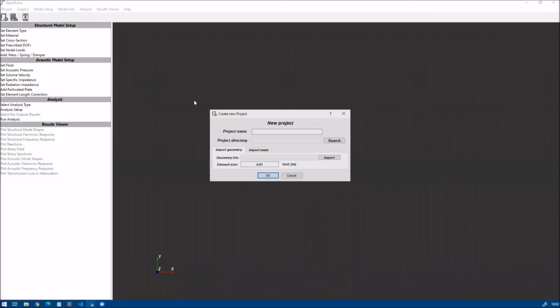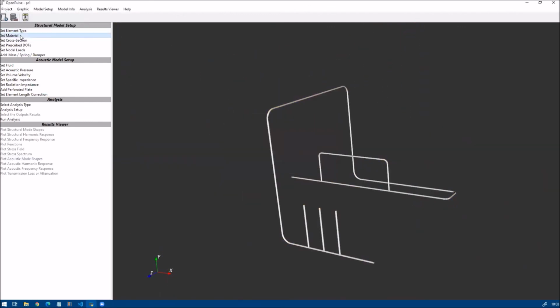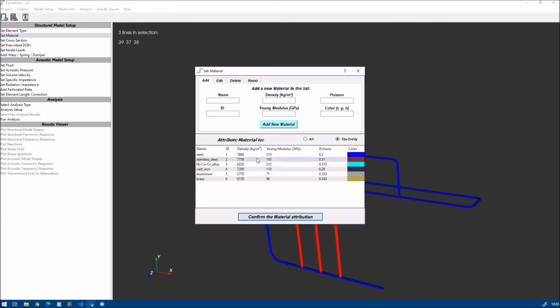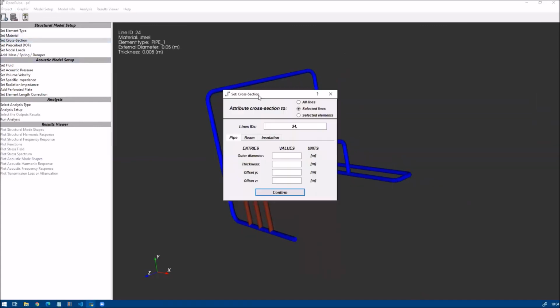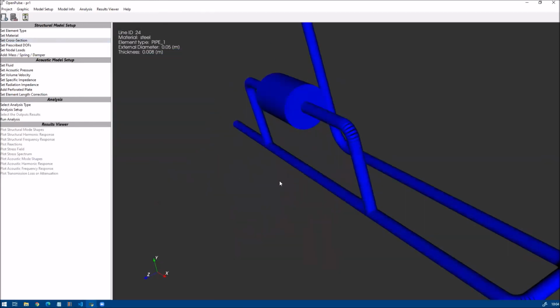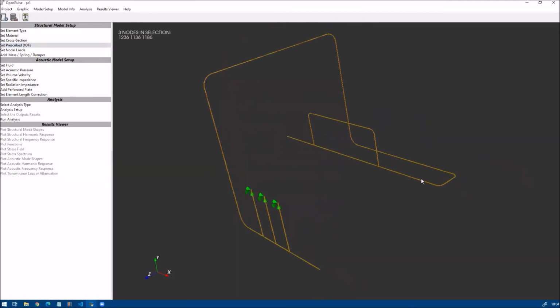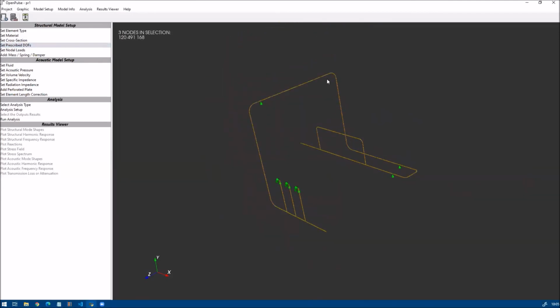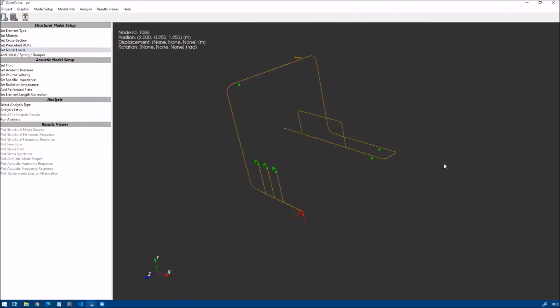This is the OpenPulse main window. You can load a geometry file and specify the length of your element. The tiles of the mesh can be thin. You can set properties for different parts of the structures, and you can set different sections. For a structural part, you can apply displacements, boundary conditions, constant or from tables. You can set springs, mass, dampers, forces.